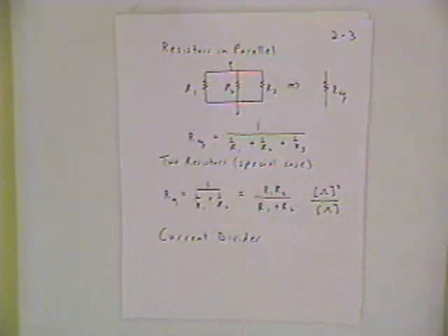This is an expression for resistance. I just want to caution you, and the reason I mention these units is to caution you against extending the special case rule to more than 2 resistors in parallel. I've seen this mistake on a lot of exam papers.